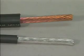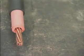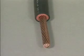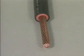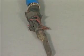The maximum amount of current that an insulated conductor can carry without overheating is called its allowable ampacity. In addition to wire size and composition, a conductor's allowable ampacity is also affected by its insulation. That's because it usually takes less heat to damage insulation than it does to overheat a wire.